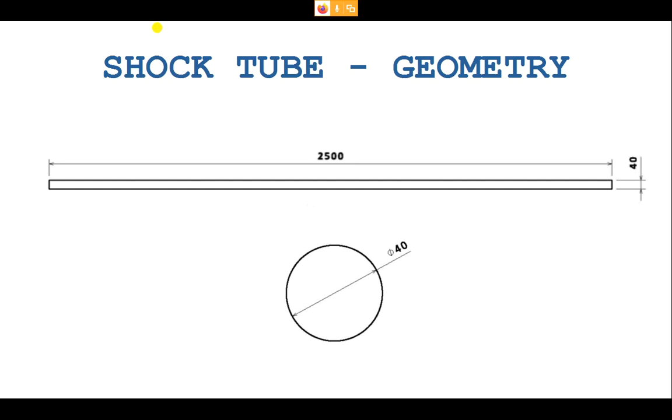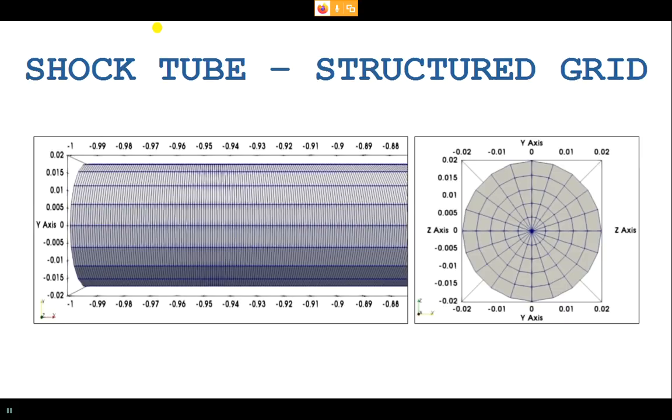The geometry is very simple. Whenever we use a geometry in CFD, we have to discretize it, that is, divide the entire domain into smaller and smaller cells, and then solve the governing equations in each and every cell to get physical properties at each point of the domain, and then do post-processing to come up with solutions.